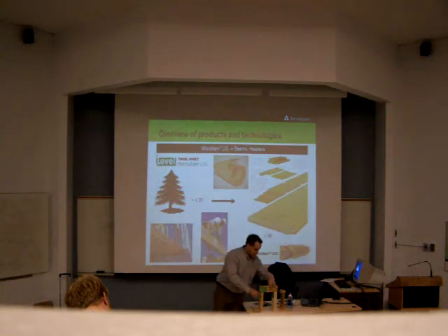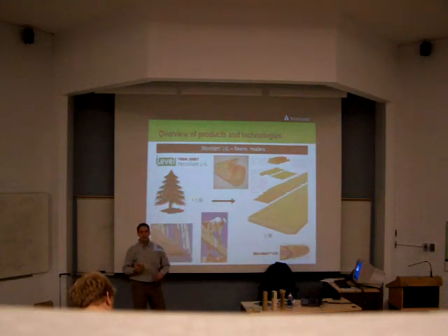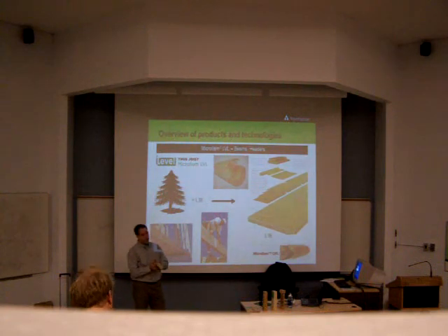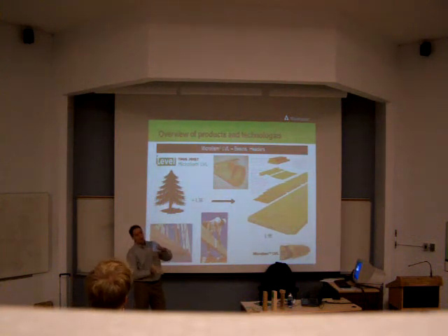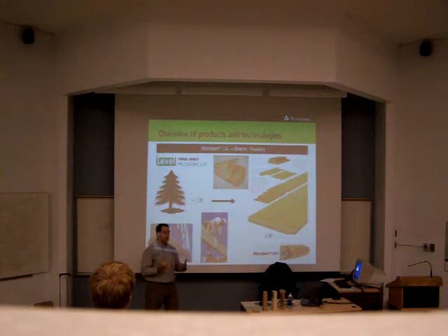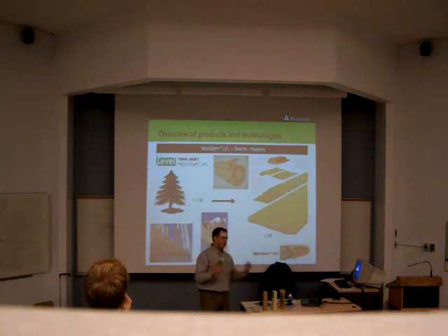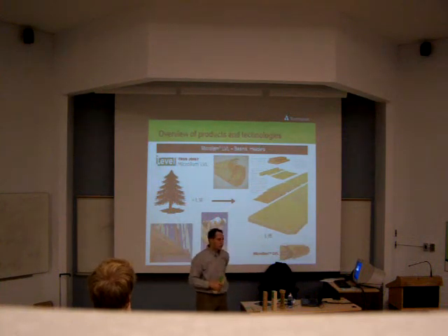Now, what was innovative at the time when this was invented, back in the early 70s, I think it was, plywood existed back then, but the manufacturing process is such that there was a limit to how thick you can make this before the hot plates coming on the top and bottom would burn the veneers before you can cure the inside grooves. So the manufacturing process, what we know today as LVL, was the innovation at the time. And now many other manufacturers make it as well.